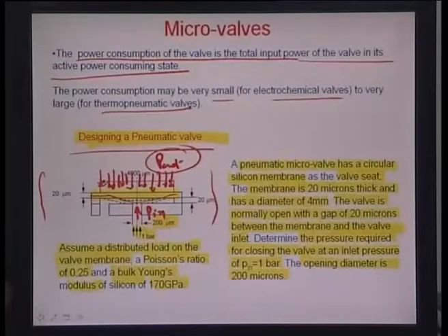This is at equilibrium, okay. This right here is an equilibrium. So, this right here again is the A open, the area of cross section which is open. So, equilibrium means that the membrane is fully seated over the inlet hole, thus valving the flow, and A open is the area of the inlet hole, P input is the inlet pressure, and that plus the spring force is essentially equal to the force by the actuation pressure on the other side of the membrane.